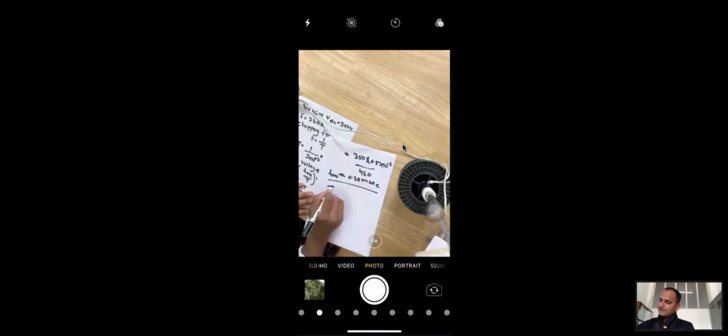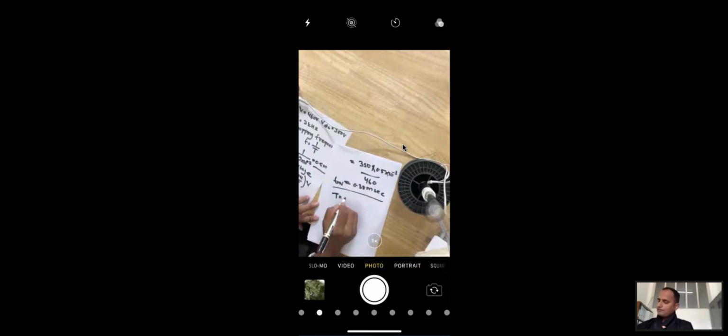So you know T is 0.5 millisecond, and T on equals 0.38 millisecond. Now we can find out T off. T equals T on plus T off, so T off equals the total time 0.5 minus 0.38. So we can find out T off also.